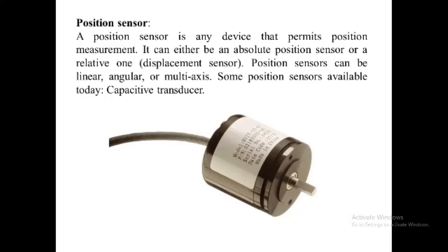direction of the movement. The phase of the output signal can be compared to the primary coil excitation phase, enabling suitable electronic circuits such as the AD592 LVDT sensor amplifier to know which half of the coil the magnetic core is in, and thereby know the direction of the movement.